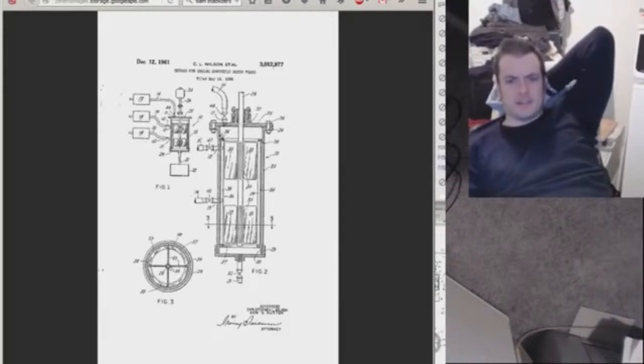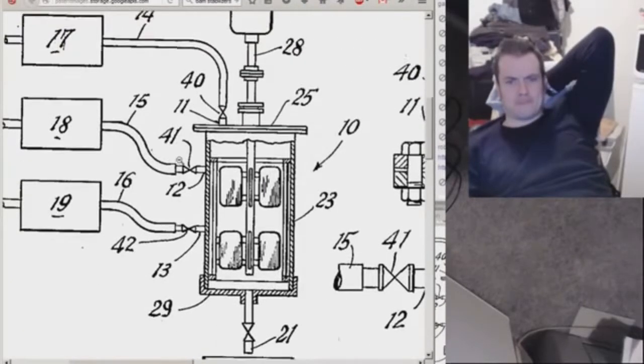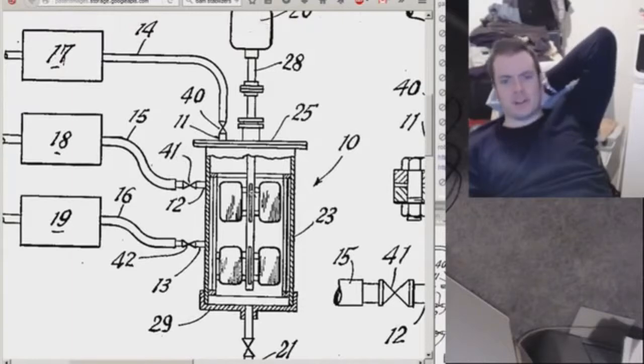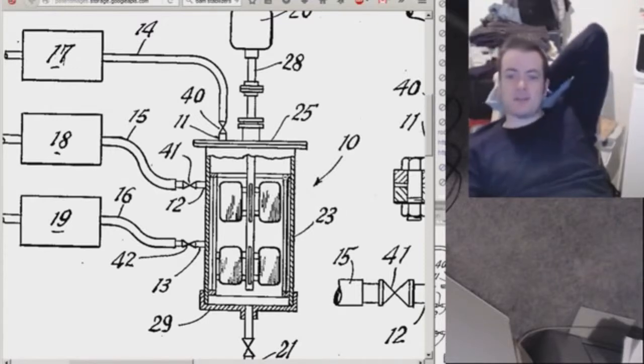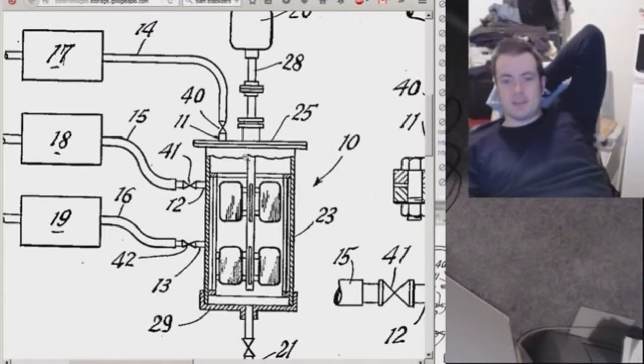How does it work? So basically, you've got a motor and a motor shaft. It turns inside this cylinder, spinning these fins around. These little walls are called baffles. They help agitate the spinning a little bit better. This is a pump, and it pumps molten foam through this tube, inserting it into the top until you fill the container with molten foam.